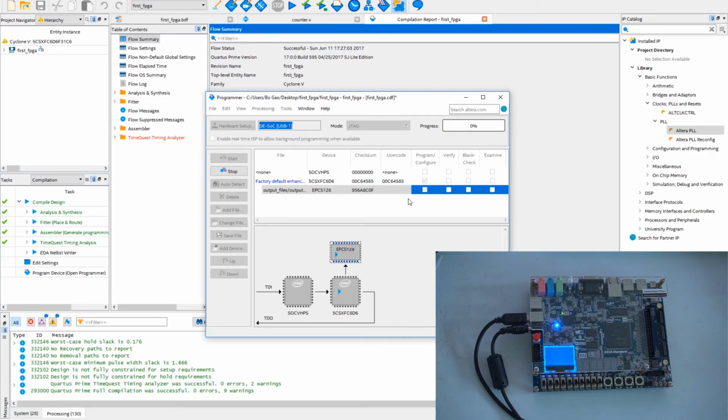So the way the JIC works is actually the JTAG first downloads an EPCS writing algorithm to the FPGA chip, and then it will talk to the FPGA chip and say, okay, with that particular IP block, I'll feed you in some data, and you put that data into the EPCS chip. So that's why it's called indirect programming. And in this way, you can actually program the EPCS without having a direct connection to the EPCS device. You just have to program through the standard JTAG interface.